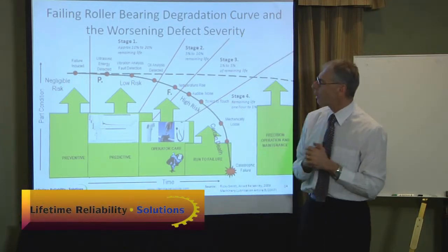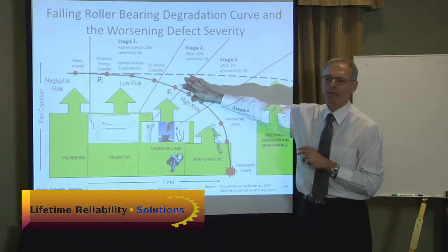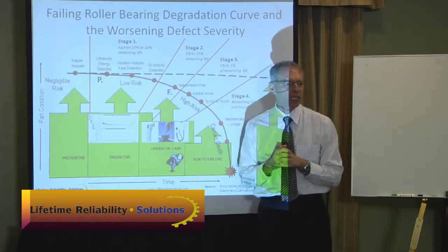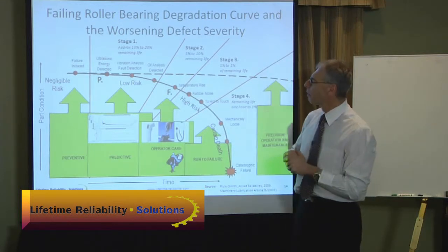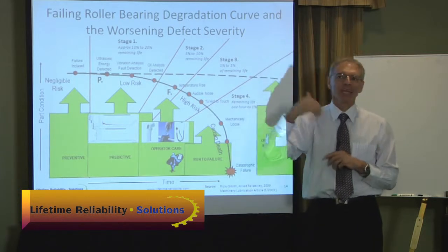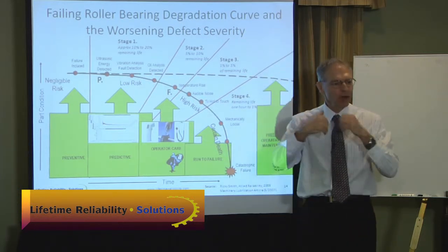Or I can have a technique where I actually wait for the bearing to fail, and at this point here, when it becomes obvious to the operators, I can maintain the machine in this situation too. But if I maintain a machine close to the F point, then it means internally in the company, I will have to have the parts. Got to have the parts on site.